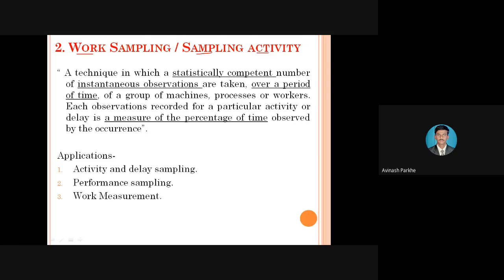What is the meaning of that? Whenever operators are working on any type of machine, how much amount of time is required to complete that particular task by that operator, that we are calculating. Also, sometimes the machines are continuously working. At the start, in the morning, we start that machine, and in the evening, we stop that machine. How much amount of time that machine is in working condition, that also we are going to calculate by using this work sampling technique or the sampling activity.